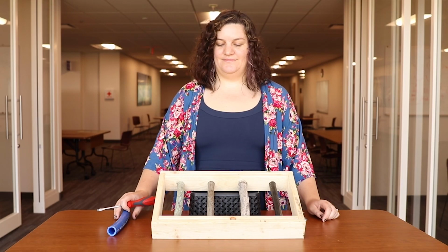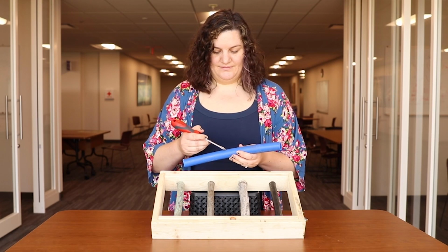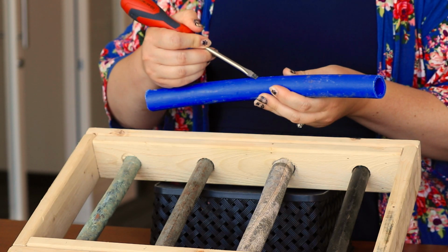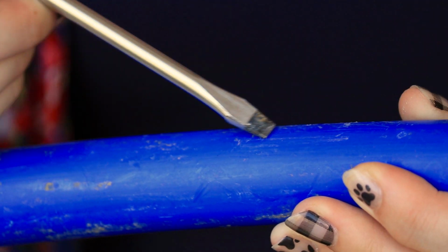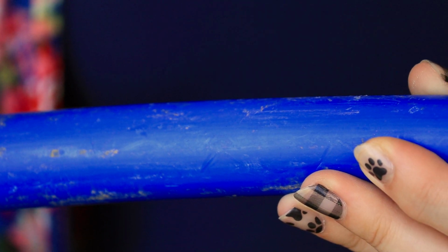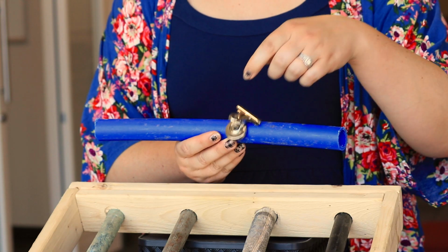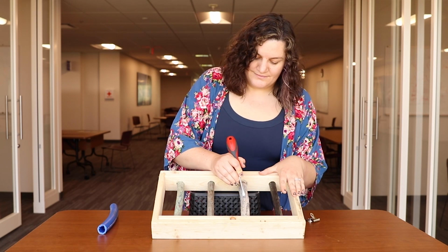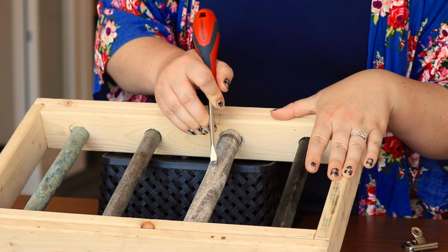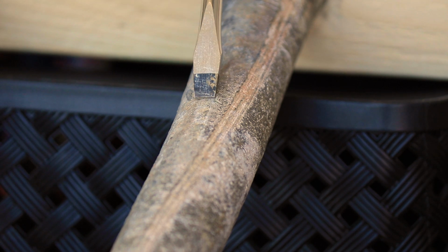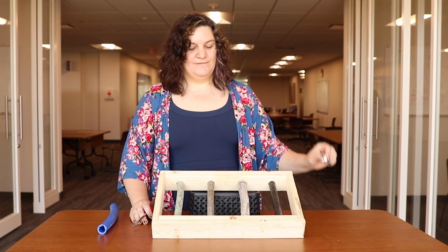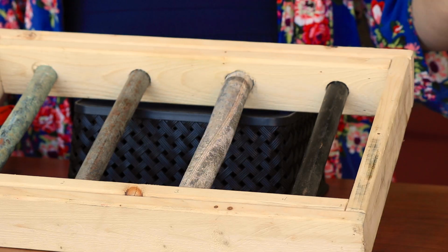A plastic service line is typically white, black, or blue. You may easily recognize plastic pipes from metal pipes without a scratch test. However, if you need a scratch test, the scratched area stays the same color as the pipe itself. A magnet will not stick to plastic pipes. If the scratched area is shiny and silver, the service line is made of lead. Lead pipes are also softer and easier to scratch than copper or galvanized steel. A magnet will not stick to a lead pipe.